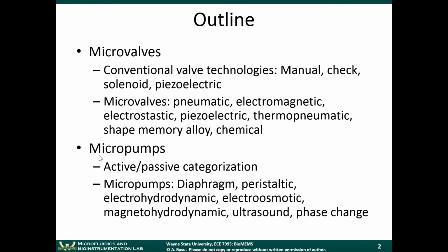Micropumps, same thing. There will be some types of pumps which are simply miniaturizations of conventional pumps. There are also some types of pumping mechanisms which take advantage of the microscale. So they take advantage of the high surface area to volume ratio in microfluidic devices.